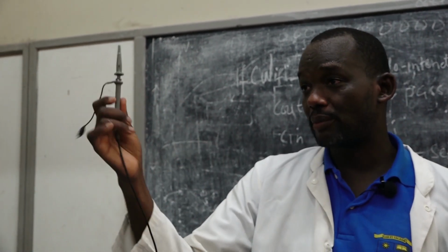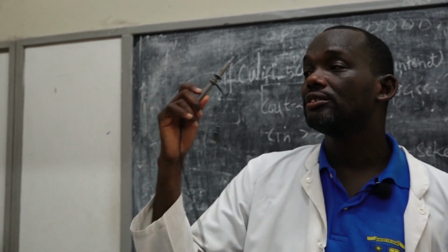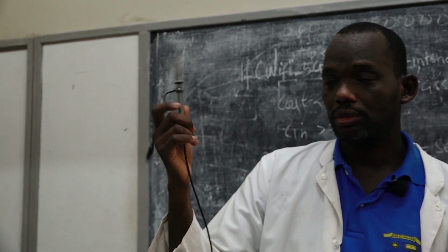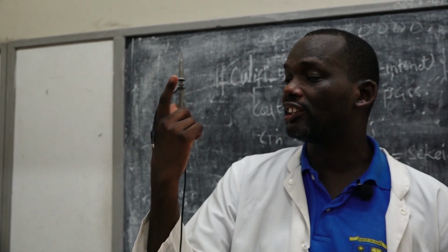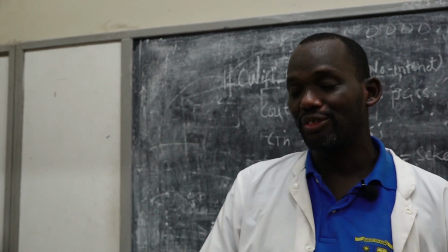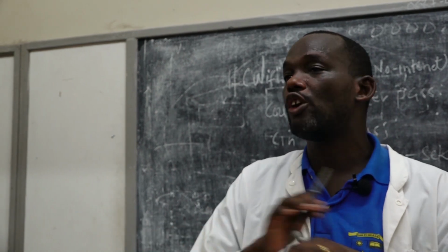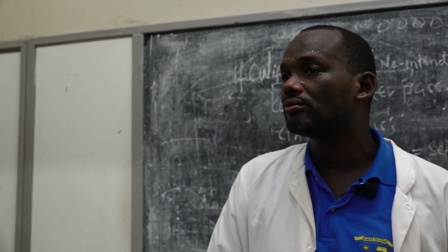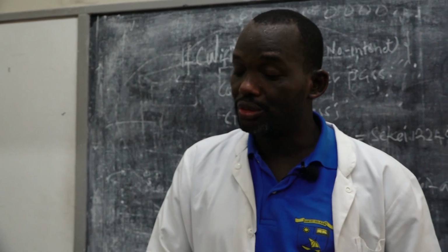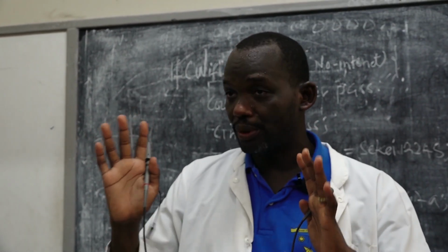You will see the switch to change the attenuation setting of your BNC probe. You have to set it to times 10. If you don't follow this instruction and set times 1, you are going to get completely different readings, and you will never accomplish what you intended. Are we together? That is the first thing I have to present to you.